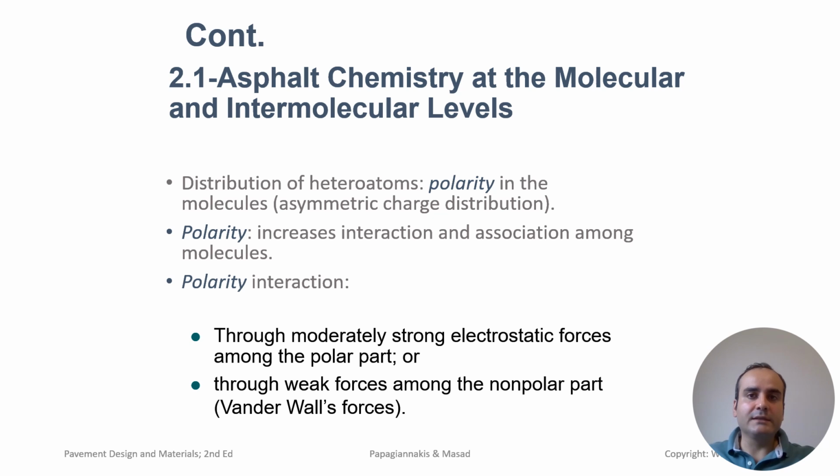Asphalt molecules can exhibit polarity, meaning that they have uneven charge distribution. This polarity increases the interaction between molecules, particularly through electrostatic forces. Asphalt's molecular interactions can occur through either moderately strong electrostatic forces between polar molecules or through weak forces such as van der Waals forces between nonpolar molecules. Polarity plays an essential role in the binder's performance, especially in terms of adhesion to aggregates and resistance to moisture.